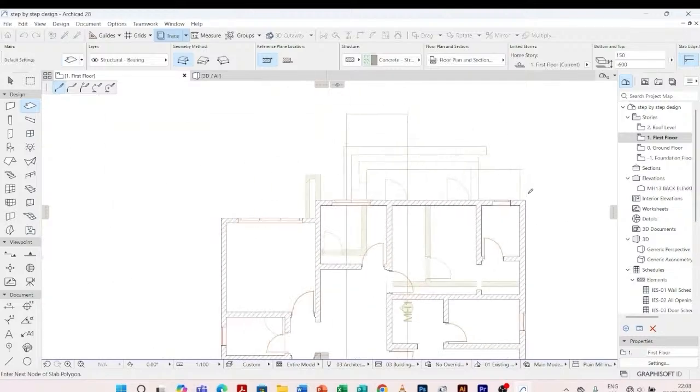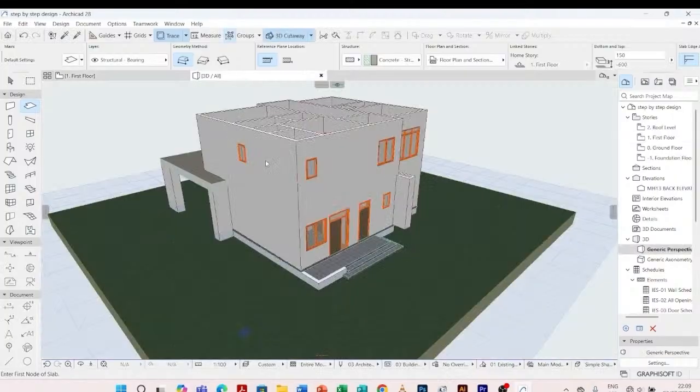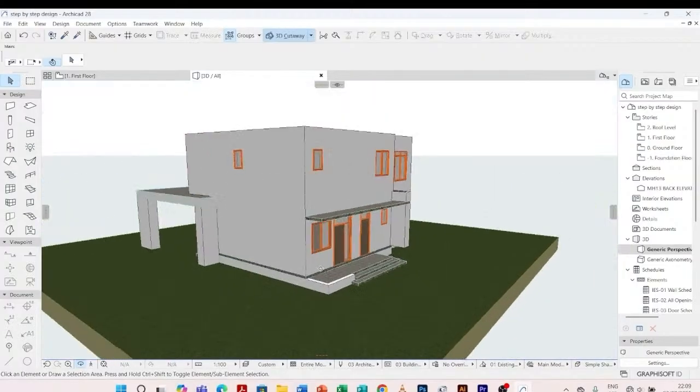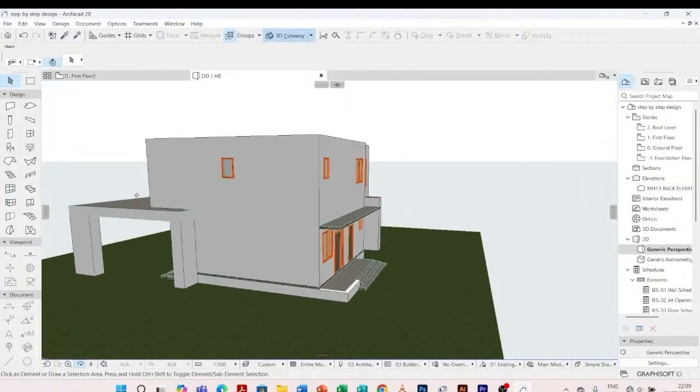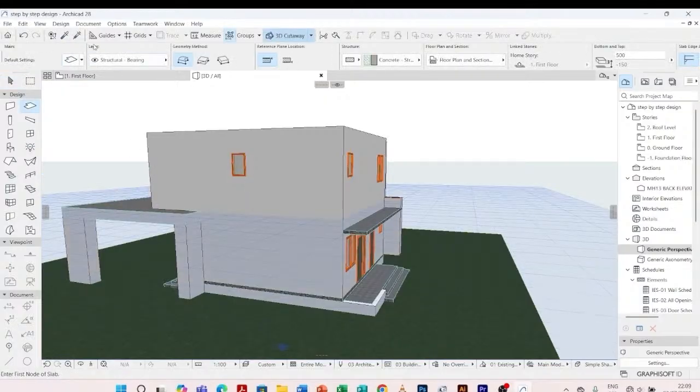Click that, come here, join this, then finish from here. So I'll come to my 3D, I'll have this slab, but then I want to copy parameters of this slab to this one. So I'll come, I pick parameters of this, I inject it in this slab. So I'll have that slab like that.